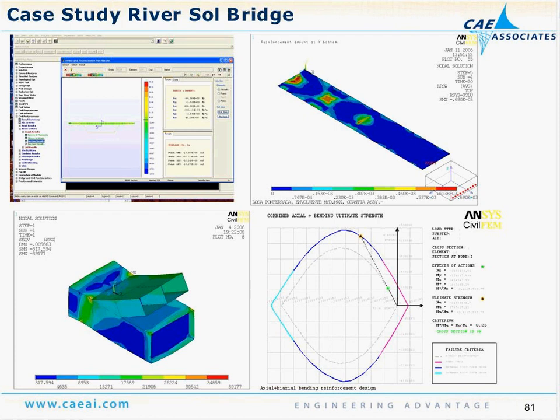And the left corner shows a sub-modeling approach for the tie between the arch section and the box section of the bridge. And so displacement response from the global model was imposed in the local model, where now we could develop the detailed stress results. Those are von Mises stresses in the actual connection, which is modeled explicitly with shells.